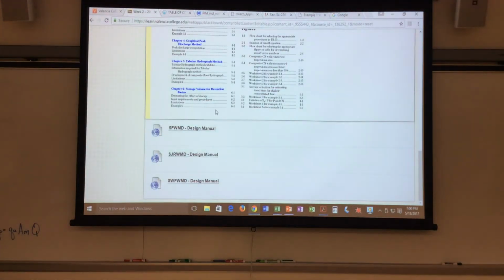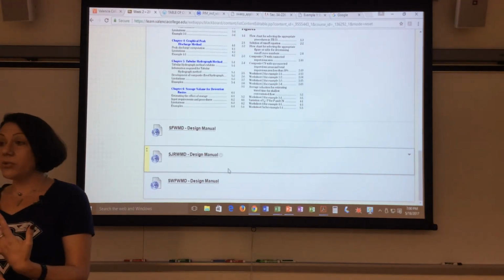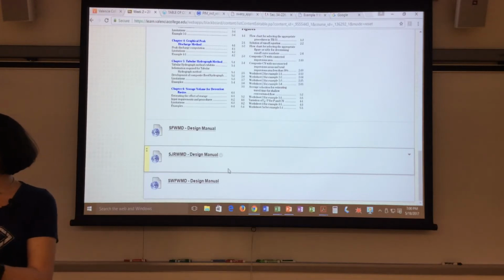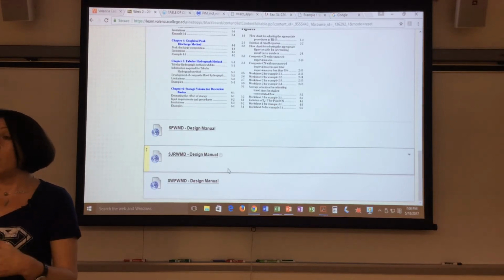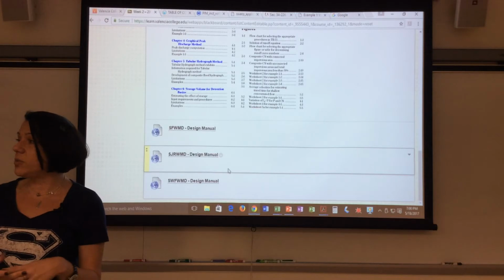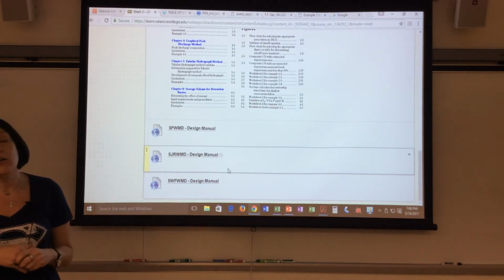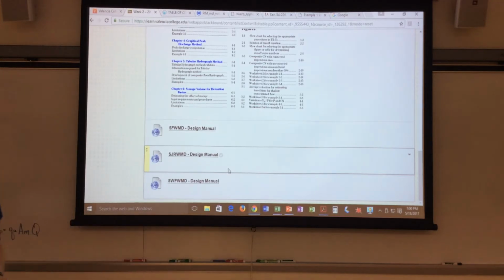So when we're talking about jurisdictions, we're not just talking about designing something. We have to figure out what design storm event they're actually going to. Some of the agencies even tell us they want their control structures to look like this for maintenance issues. They don't want this or that, and once we get into the hydraulics part of it, I'll go over the control structure and what the agencies require on that.